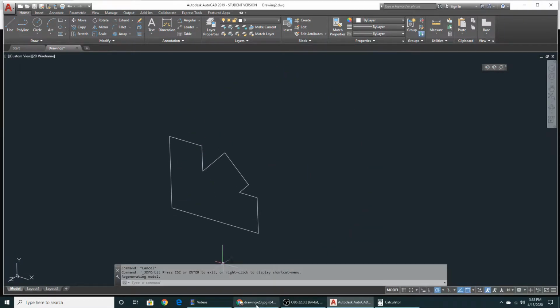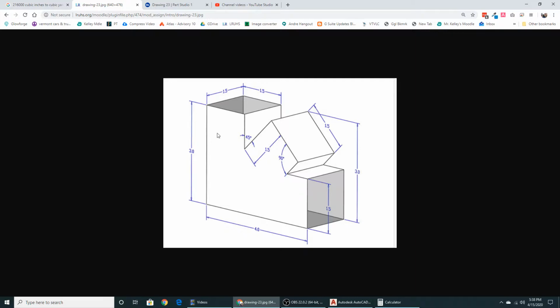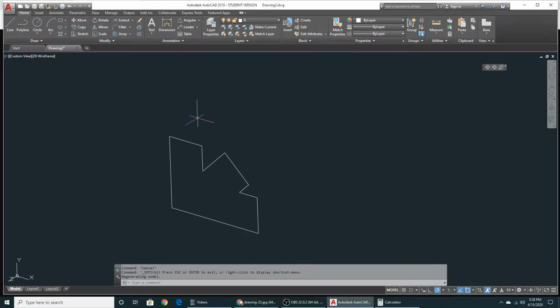If you recall, it's 1.5 inches thick. So I'll jump back here, and I'm going to throw a line in and make sure it goes in the Z direction. Now notice right there it says we're polar 1.67 and so on. If I move my mouse it changes, but it does say that the angle is negative Z. That's what we want. We definitely don't want to eyeball something that looks like Z and not have it snap in that Z direction. You can see the blue, green, and red lines on my icon as I move around. That blue line is Z. So just make sure it lines up with blue. It should snap into place if polar tracking's on. And just type in the 1.5.